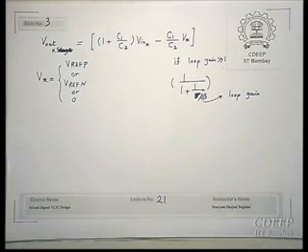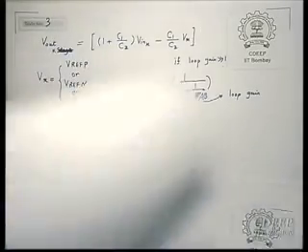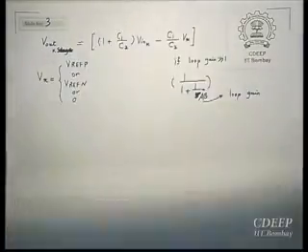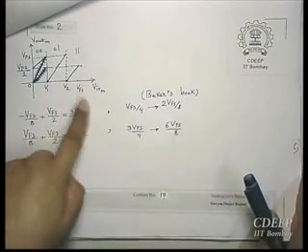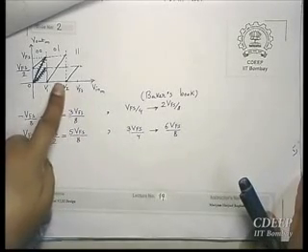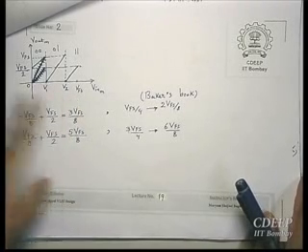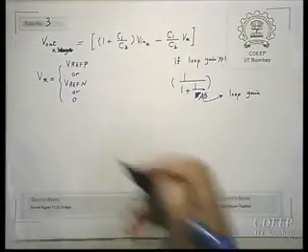So what kind of conversion would it be? We had it in the previous slides. So this was for single-ended. Do you remember this was for single-ended, if we have 2 bits per stage. Now if you want to make it differential, shift this plot to the left and down, so that instead of 0 to V full scale, you will have between minus V full scale by 2 and V full scale by 2. So you will get this.